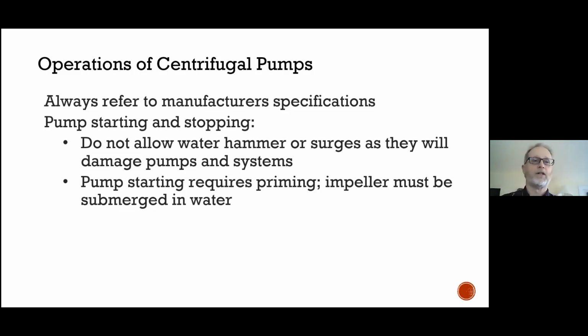Another key factor when we're starting or stopping a centrifugal pump, the pump needs to be primed. It needs to have a flooded suction, right? The pump, if the impeller is not submerged, then it will become airlocked and continue to spin and heat up. Doesn't necessarily damage it right away, but there needs to be an alarm or some signal back to the pump mechanics to let them know that the pump is not actually moving any water.